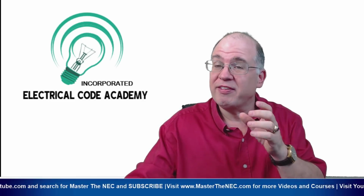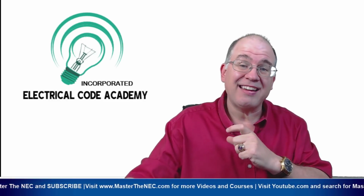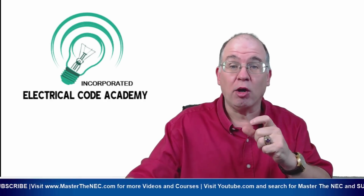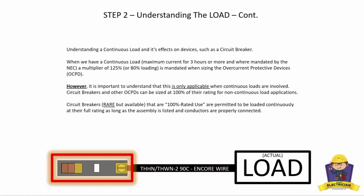Because ultimately, when we size a conductor and we apply all these derating factors, we have to make sure that this new conductor has an ampacity that can, one, handle the actual load, and two, be protected by the overcurrent device. That's important. So we've got to tie all those things together at the end. So let's look at the presentation a little bit more.